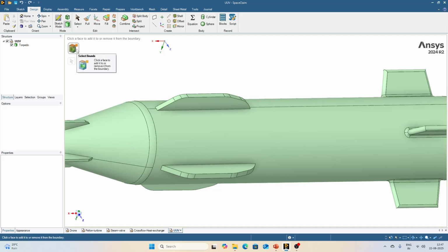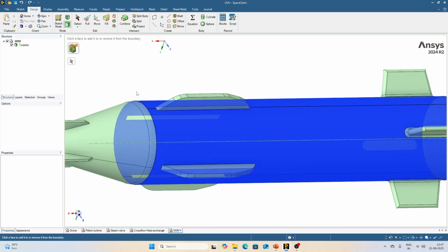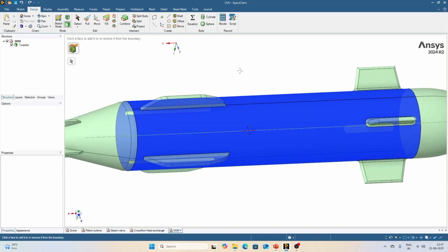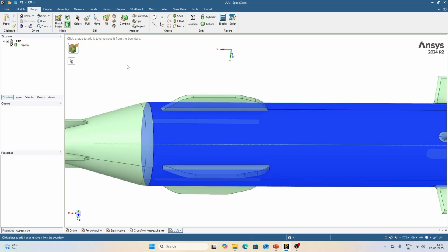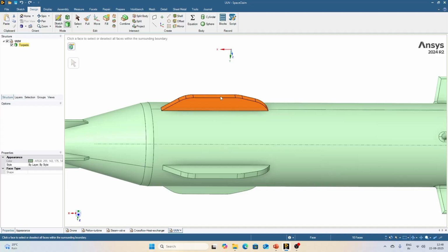First we need to select the boundary. As you select, you will notice the color changes to blue. Let's select the seat surface. That will be on this rib. Once you click on the rib, the boundary faces selection will disappear and all the faces of the rib will be selected. So this is our selection which can be used for any particular operation.